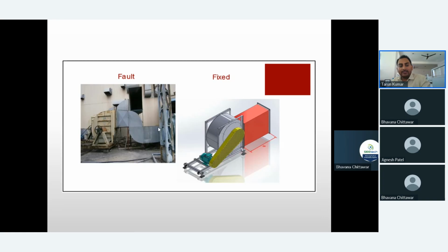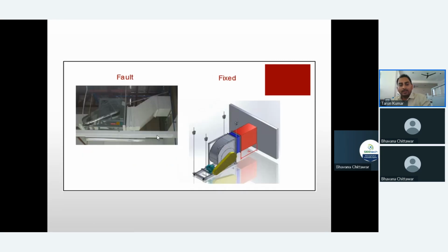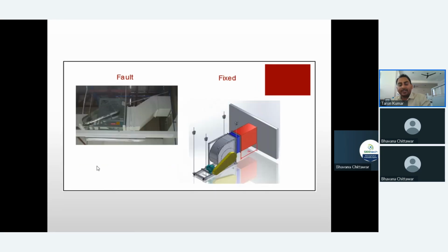Then further to that, you can see this again. They had taken the 90-degree fan orientation; instead, they would have gone with the 270-degree fan orientation, and these immediate 2-3 bends would have been avoided, and your power consumption becomes lower than this system. So you can see the other photograph also. Here they have taken it wrong. It should have been 270-degree rather than 90-degree, and here they have taken 270-degree rather than 90-degree.